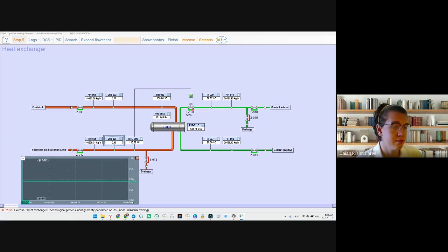Yeah, 0 means that all products are in liquid phase, 1 means that all stream is in vapor phase. And sometimes operators should condense the product as much as possible. So we need to increase the quantity of cooling agent, cooling medium, when we condense maximum raw material.